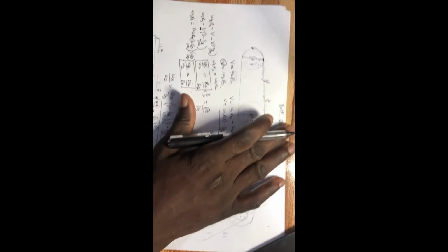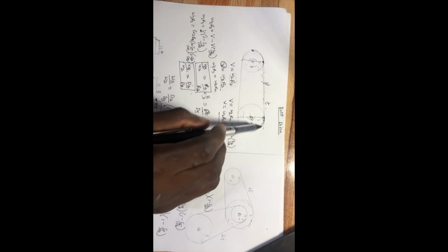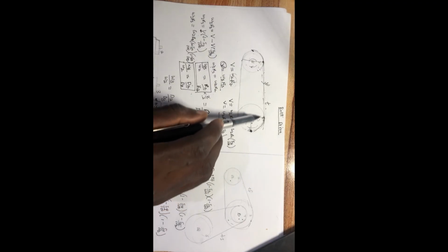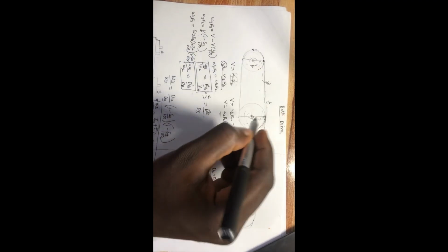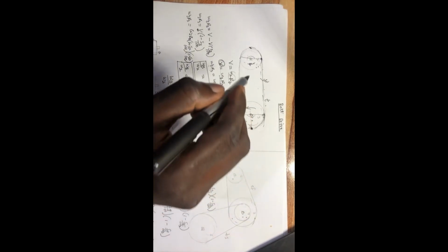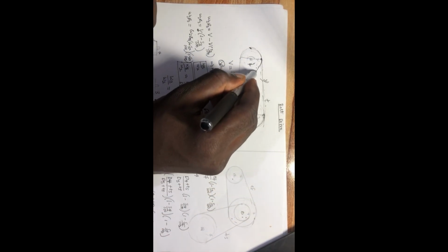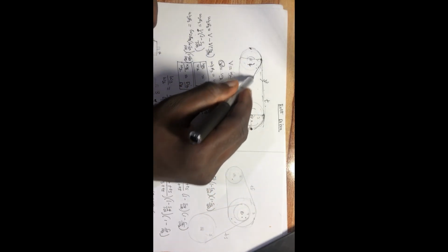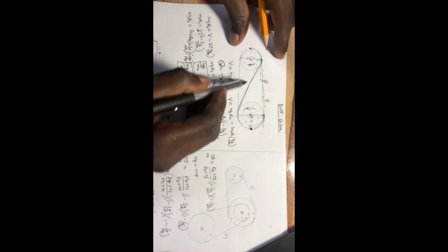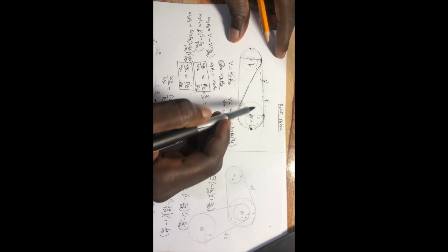Now here, let me talk about the different motions. So you see here, the belt is not crossed. So if the belt is moving in this direction, it's going to turn the pulley around like that. So this one will move in the same direction. But suppose this one is moving this direction, and I want this one to go the opposite direction. I will let the belt pass here, touch it, so it will come here and then go this direction.